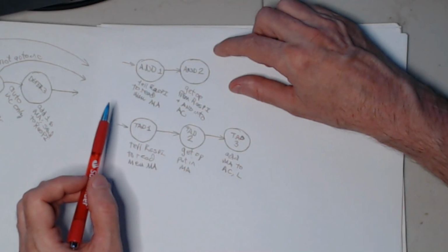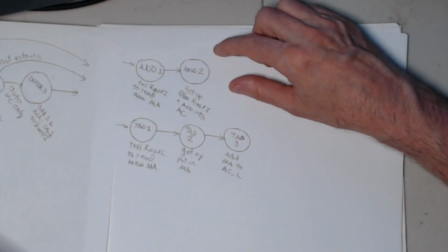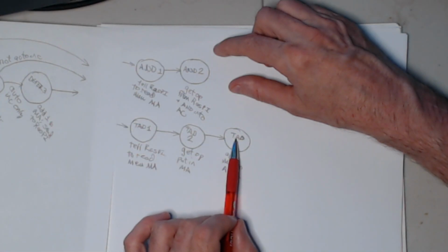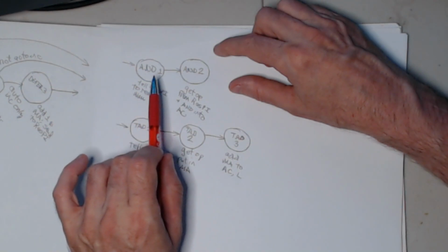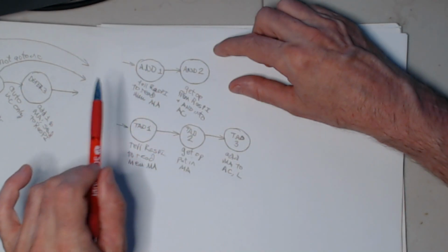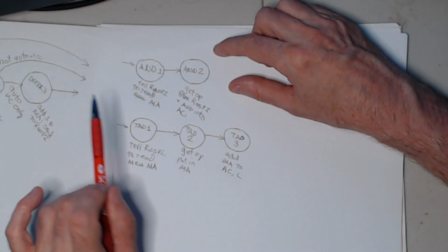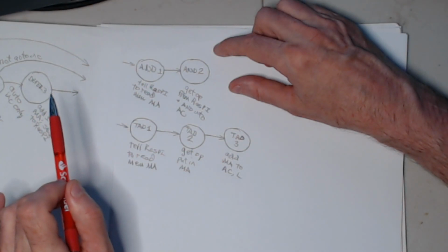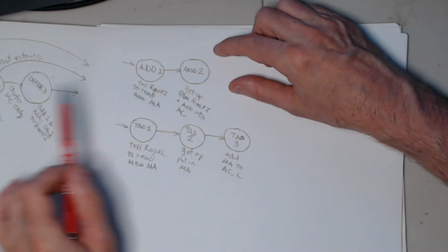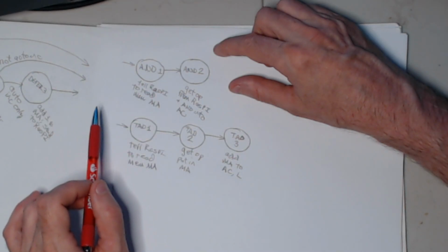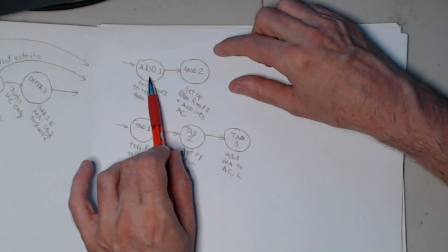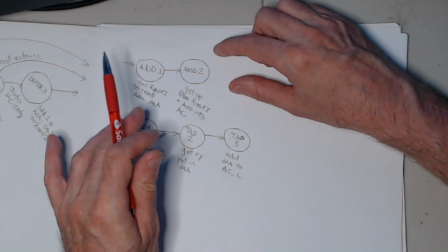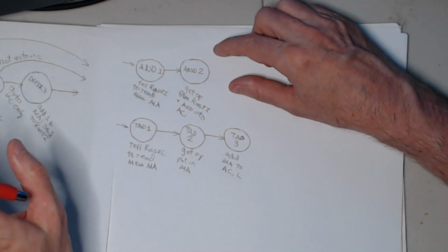Because if you know the accumulator is 0, it's not going to take any time to do any carries, so we're not going to need to waste time doing this. Doing a TAD to an accumulator of 0 is exactly the same as doing an AND if the accumulator is all ones. So it'll actually go and do these AND steps if the accumulator is 0, and just pretend the accumulator had all ones in it.